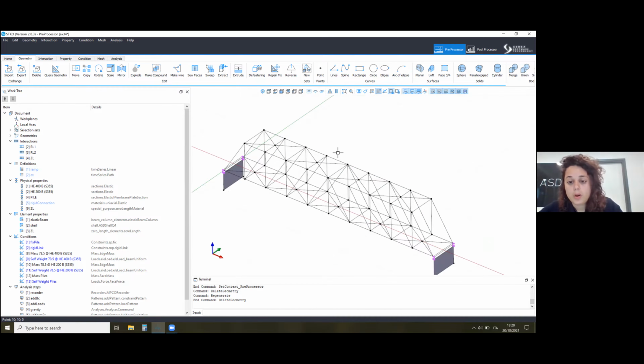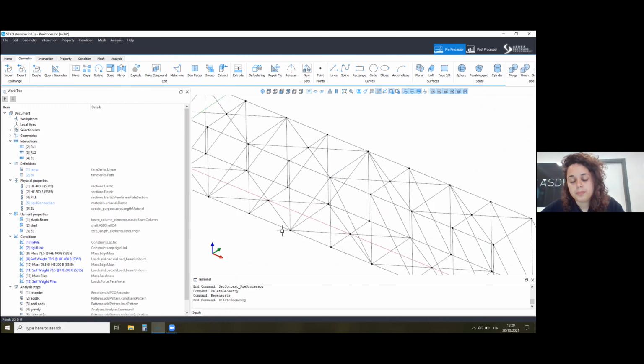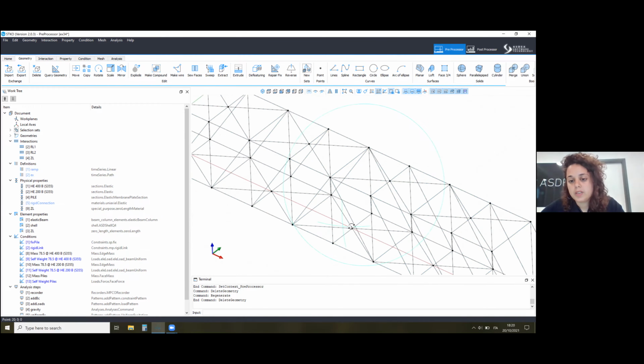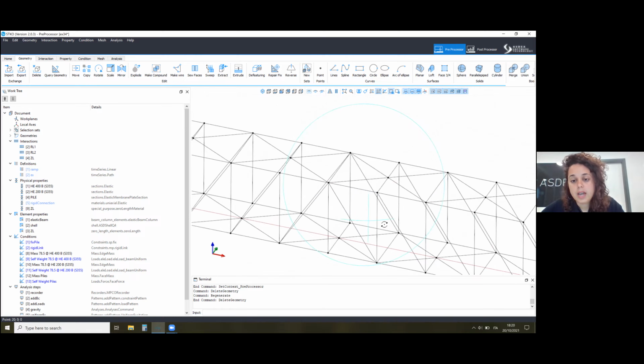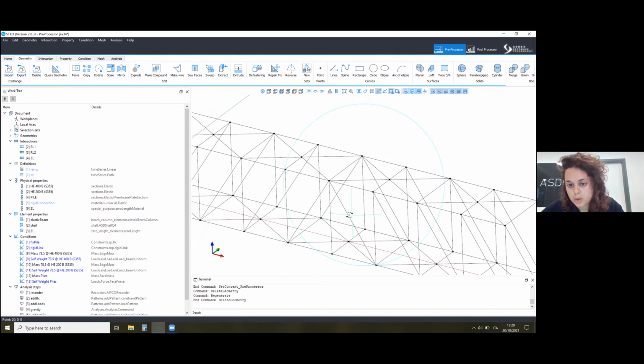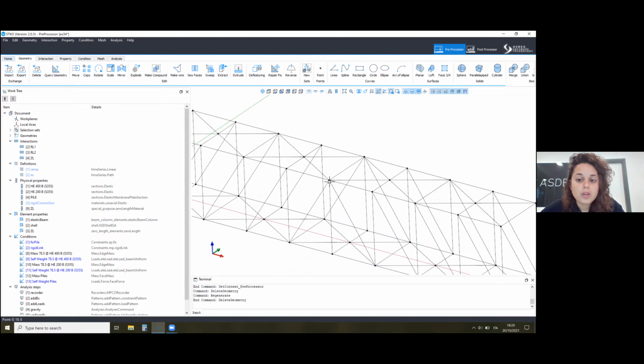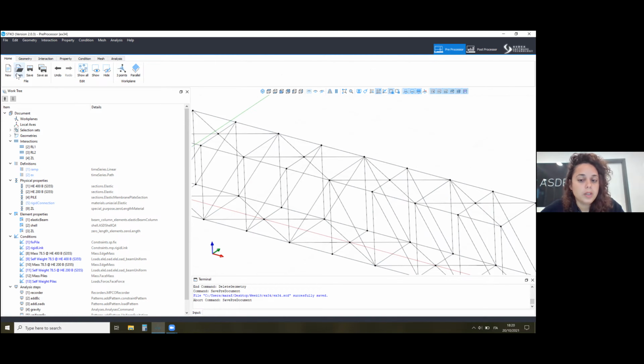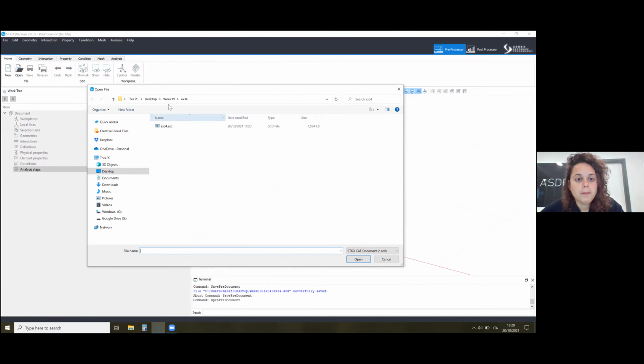Something that is so often done in the bracing is to release the rotational degrees of freedom and make these elements behave only with a specific axial stiffness and maybe a torsional one, but not a rotational one. If you know the stiffness of the joint, this is something that you can also input. I will show you with my next example. It's the same exact passageway, but it has an addition.